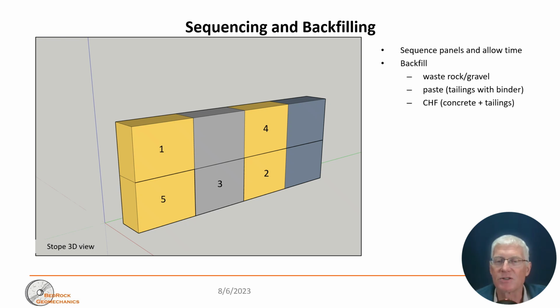All kinds of procedures involved around that, and a lot of interesting rock mechanics that has to deal with it. Not simple, but probably an important thing to be doing in most mines. Then the top item there, sequencing of the panels where you're stoping, and then allowing time is important. So you can model this using computer modeling techniques of the evolution of the stresses and strains, and come up with beneficial ways to sequence.